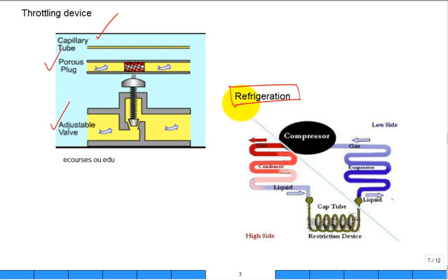Anyway, a lot of times in home refrigerators, you can find the capillary tube very easily. It's just a coiled up thin copper tube, and if you can trace the refrigerant, it flows out of the condenser through the capillary tube, and in the capillary tube there's a pressure drop, and the liquid is basically ready to evaporate in the evaporator.